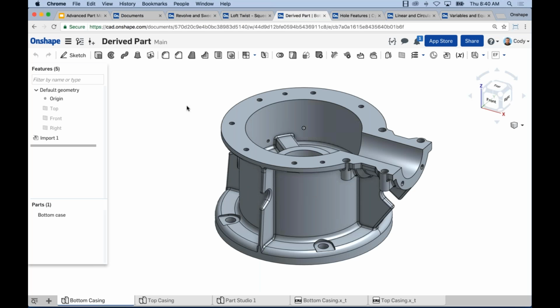Now, there are a few examples where this is useful, and we can get into even more advanced examples of this. And I'd recommend if you do a lot of designing around multiple parts, do a search for in-context design as well. Do some research on in-context assembly design. But if I'm sent 1 or 2 parts and I need to model around those parts, derived is really useful.